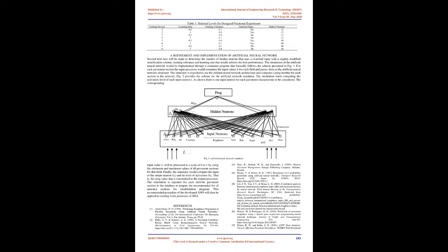Step 2. Selection of outlying road sections not included in the rehabilitation program. This is important because the artificial neural network needs to learn to differentiate sections that require rehabilitation from those that did not. All of the information needed will be obtained for all mileposts that do not have a rehabilitation programmed or constructed for the 3 years following the programming year.